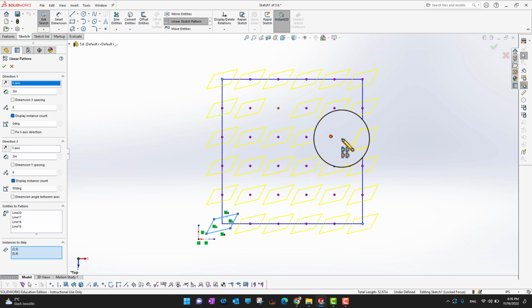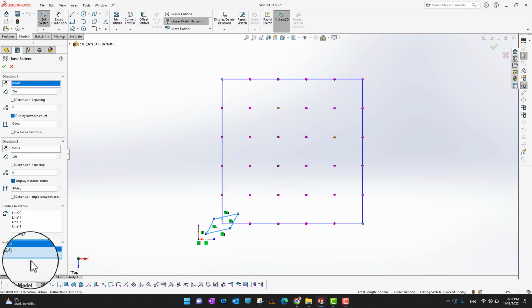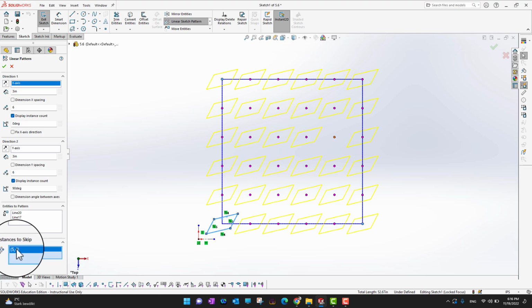Okay, so you can just click on those dots, and then those two sketches, or as many as you want to click, can be removed from your pattern. Or if you want to bring them back, you can go here again, select the pattern and delete. So it's going to come back, and again you can select this pattern number which you deleted. You can right click on that and delete it, or you can just select this and press the delete button on your keyboard. So in this way it's also going to come back.